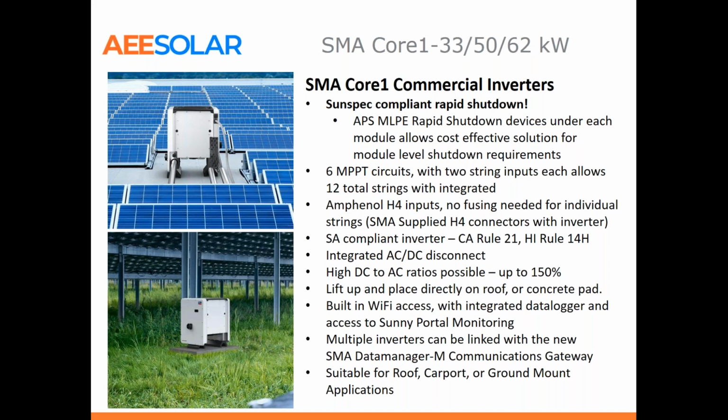As mentioned before, some of the inverter offerings we're seeing: the SMA Core 1 series of inverters. These are SunSpec. These have been out for several years and proved to be very popular inverters. We stock all 3 of these varieties, the 33 kW, the 50 kW, and the 62 kW. These output 3-phase 277/480 volt Y. Very flexible inverters. There is an SMA string designer, very easy to use. You can check voltages and module pairings with that.